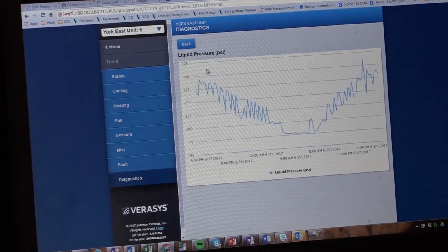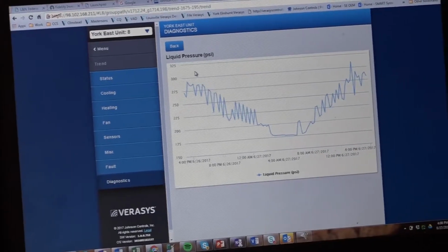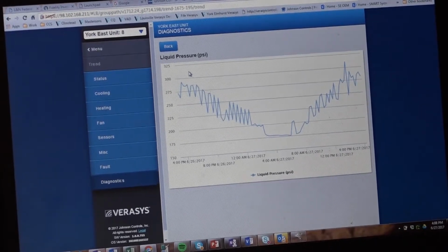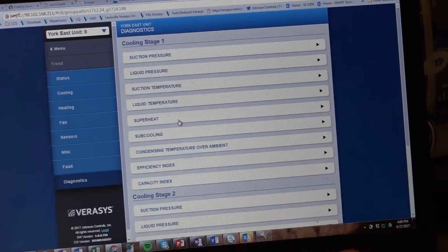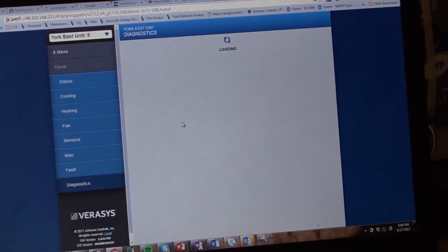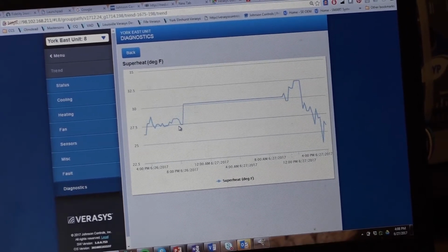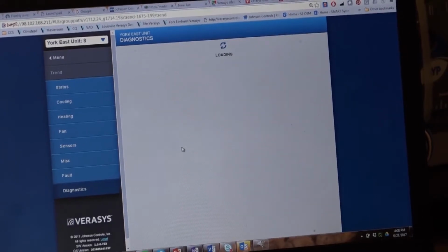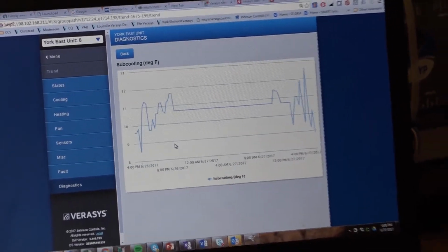In the area where I was having add charge, as a professional mechanical contractor, I should be able to really home in on these data points and be able to tell exactly what's happening. And this is the very nice thing for a mechanical contractor. We are pre-calculating all the superheat information that they need to troubleshoot the system, or the subcooling information they need for this particular system before they add charge.